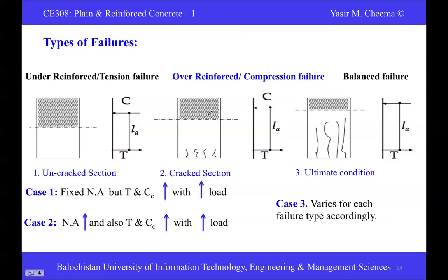No, because it's more than the balanced reinforcement required. So if more tension is produced, steel can take more tension, but cannot take the compression. No, it's to the concrete. But concrete is on the normal design. If the concrete strength is designed for, let's say, 35 megapascal, and you put a compression load equivalent to that used for 40 megapascal, 35 megapascal concrete cannot take that. Alright, that is one. So in that case, failure goes to the compression.